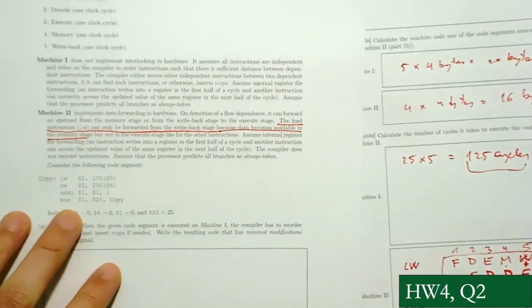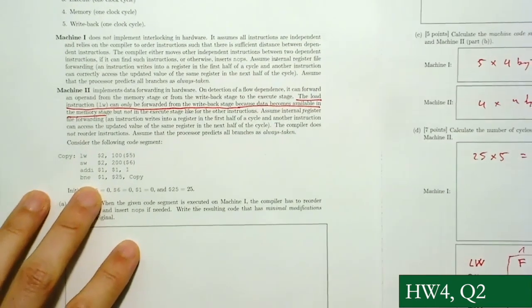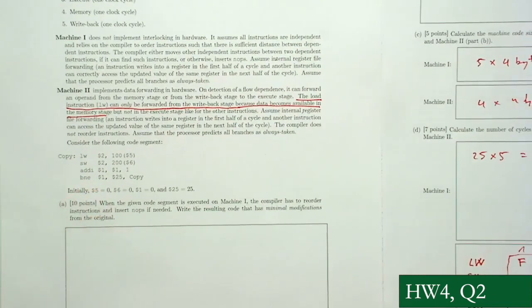It wouldn't work for me because I wouldn't have left the decode stage, because the valid bits aren't 1 yet. So there won't even be a situation where I get the data forwarded from memory to execute, because I wouldn't be in the execute stage yet. It works in the book. It has a hazard detection unit, or what it's called. Then it works.